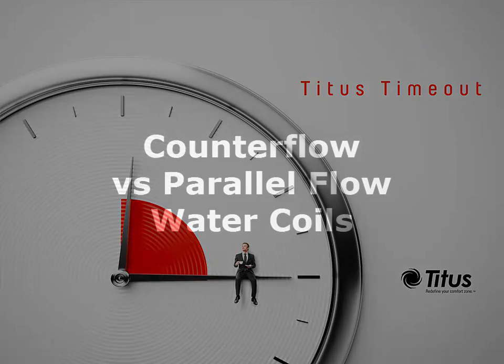I'm Jenny Abney-Civy, and today we're going to discuss the difference between a counterflow and a parallel flow water coil. The two most common flow arrangements in a water coil are counterflow and parallel flow. In a counterflow coil, the direction of the water flow is opposite or counter to the airflow. So it looks something like this.